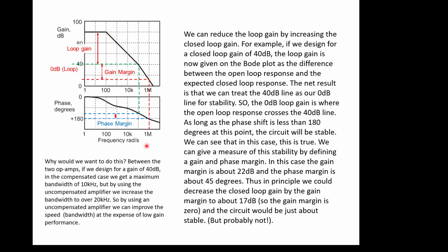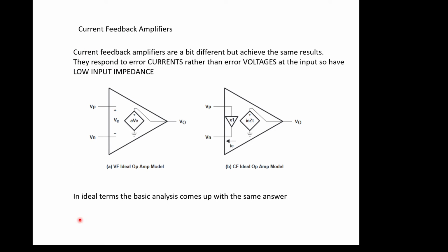But a lot of people want to build low gain amplifiers, which is why these compensation poles are built in to make it easy for people, so you don't have to worry about gain margins and phase margins all the time. But I'm sure as engineers leaving Southampton you want to know about such things, because you might be able to manipulate it to your advantage, because you've gained a doubling of the bandwidth by understanding that if I have an amplifier that's a bit lively, I can get a better response out of it, and it can still be perfectly safe to use. It's quite interesting stuff, really.